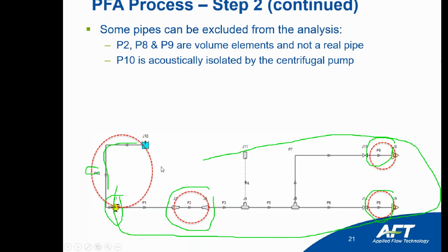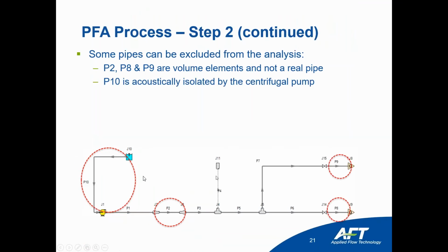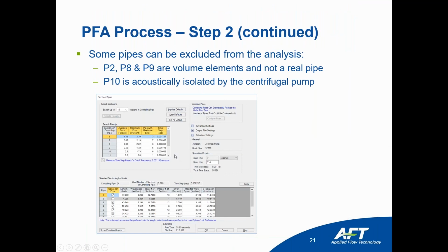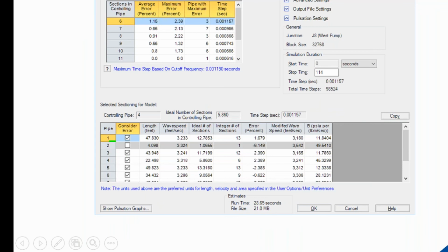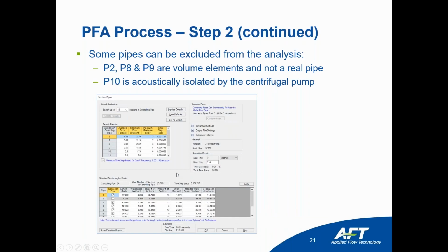Finally, we have in the other tab, the PD pump setting, where you specify all the details of the pump. So here, in this case, we have 120 RPM, bore 40 millimeters, stroke 75 millimeters, rod length 360, and so on.